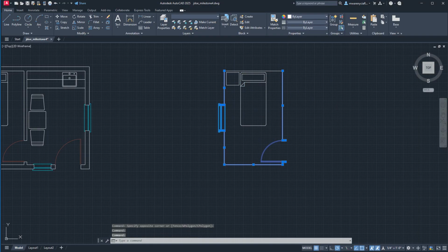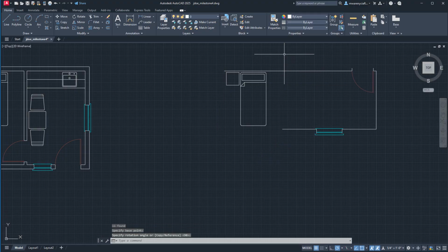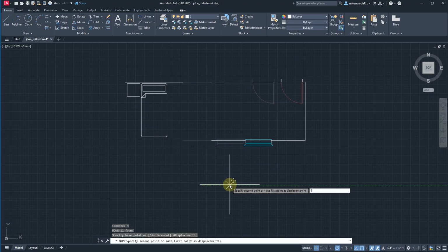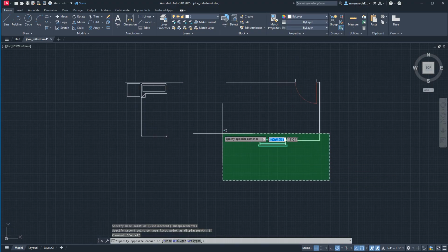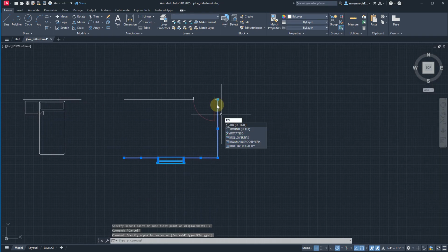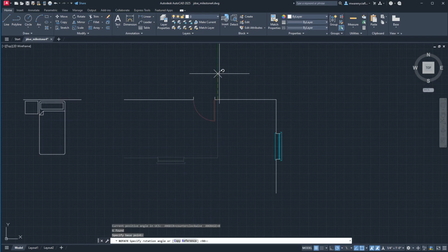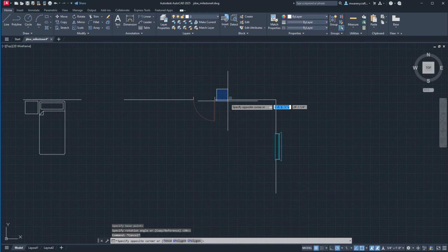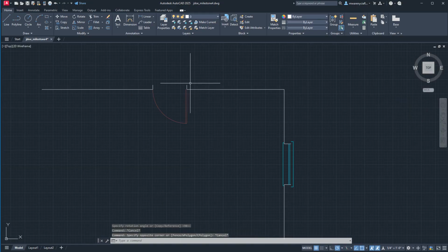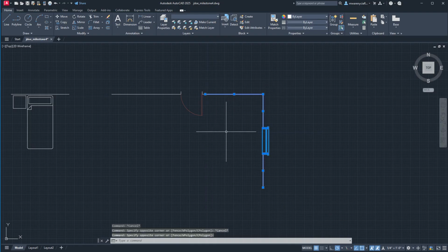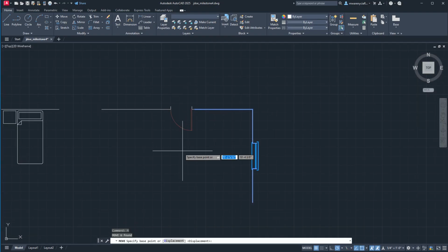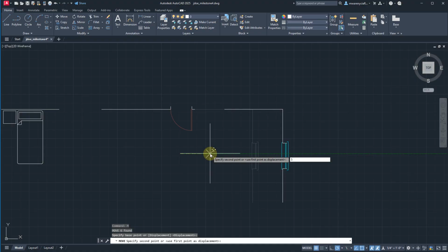What I'm going to do is a rotate. So I'm going to rotate it 90 degrees like that. And then I'm going to move this over 5 feet. And now that that's good, I see all this going on here. So I'm just going to do this next one, rotate this 90 degrees. And make sure when you do this that, like this was my rotation point right here, you do your selection so that you leave the part that's here for that door jamb. That stays there, and then we're going to move this next part over 5 feet again.